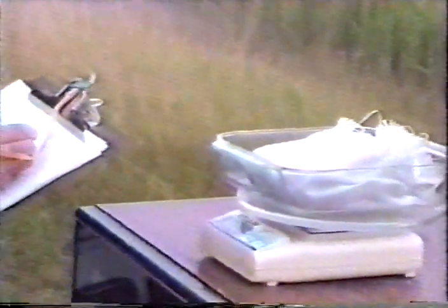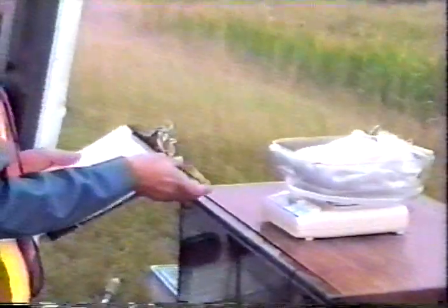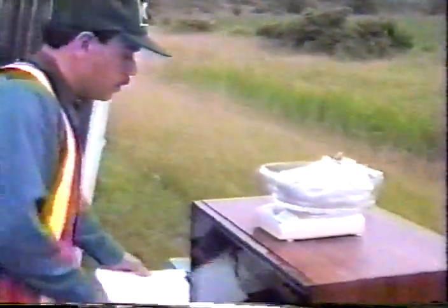The exact weight of the tray plus cloth plus fresh sample is obtained and recorded to the nearest gram. Call this the final weight, WF. The difference between WF and WI gives the exact weight of the fresh sample, recorded as WS. All weights should be measured and recorded to the nearest gram.